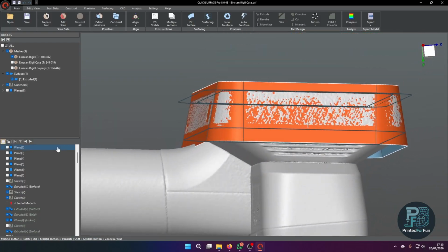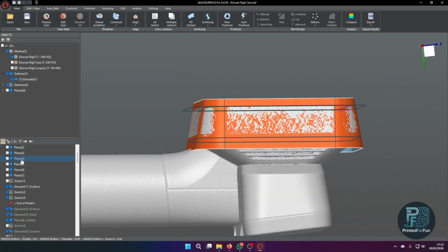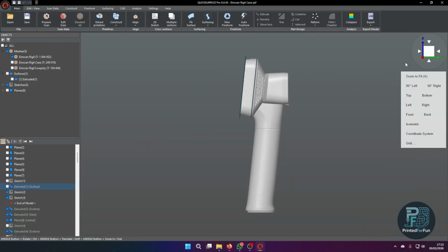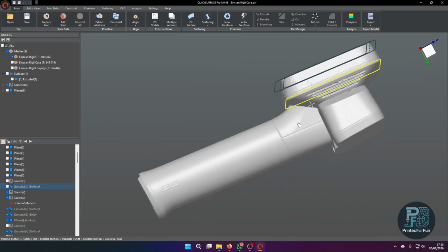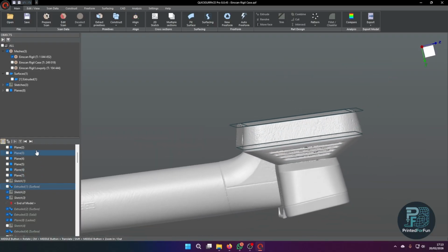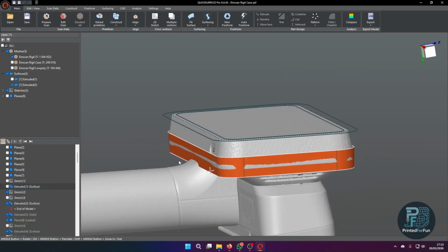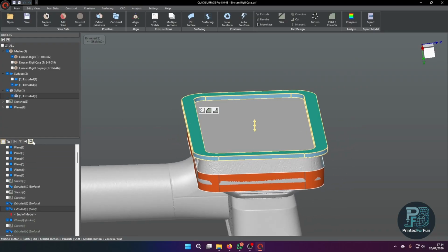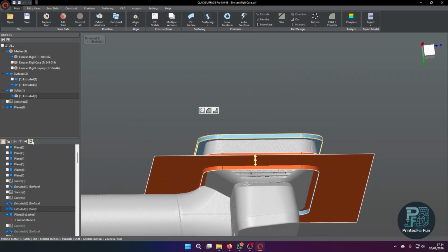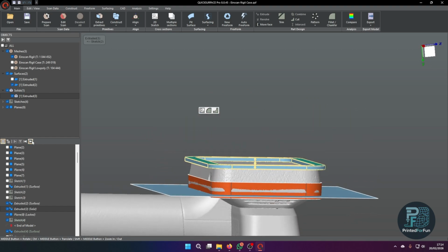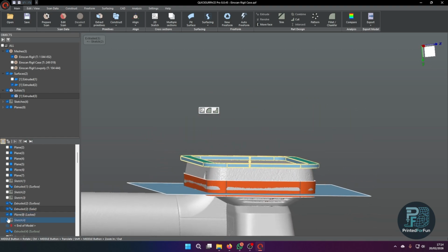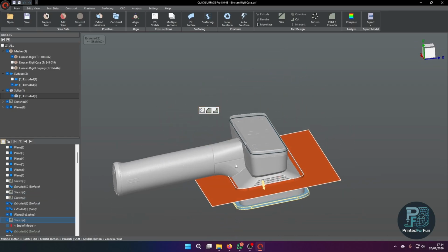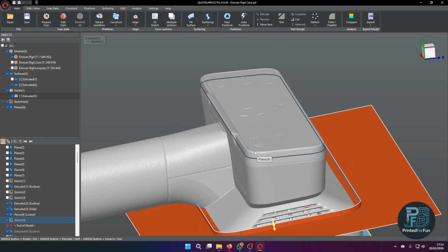And the third intersection will now be here at the straight part, I would call it, that isn't drafted, that I can just extrude as is. And then I extrude here the top sketch and create an additional plane for cutting.